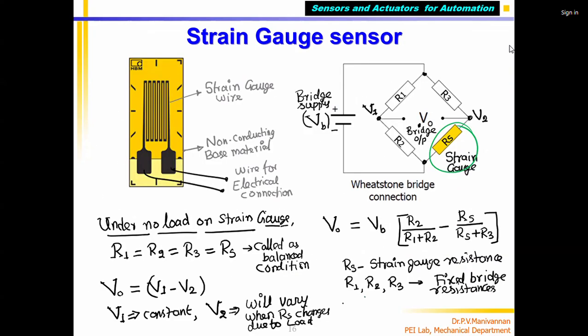Piezo-resistive effect is the main contributor, which is directly proportional to strain applied. Other thing, due to temperature, resistance can change. We know that resistance can change, like the first sensor, RTD. Similarly, the strain gauge also can change. That's why they select a special material. In spite of that, if the temperature change is too much, then there will be a change in resistance.